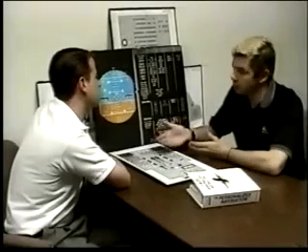Is it true that if you stay on it, it's going to drive you down the center line? If you're on it, that means you're on an appropriate heading to intercept the center line, or that you are on the center line. We basically call it steering information instead of raw data. And what if you were to lose the localizer? If you lost the localizer, but it had received it for a reasonable amount of time, it would memorize the path and still give the information required.